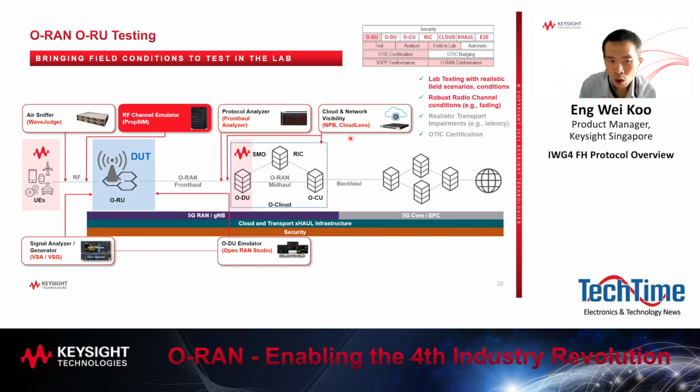Then we spoke about how we make sure that we can test the ORU not just from a functional perspective. In this case, you need to be able to create channel models which are very close to real-world conditions, because the ORU is not just designed to operate in an ideal environment. We apply a product called the PropSim solution, which gets connected here to the ORU, so that we can have realistic channel models emulated. We can performance test the ORU.